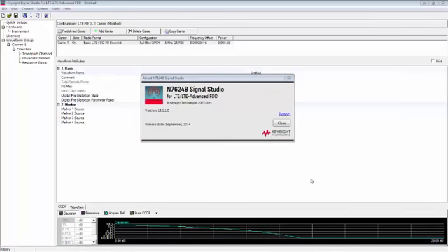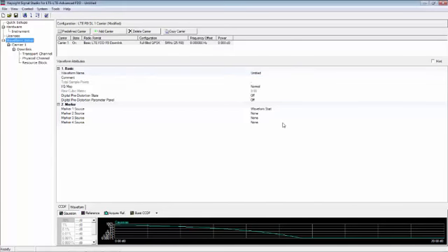Let's create a 10 MHz LTE FDD E-UTRA test model 3.1 downlink signal with the Signal Studio software. So let's get started. First, I'm going to set the basic parameters for the vector signal generator in the form of frequency of 2.14 GHz and amplitude of 0 dBm.